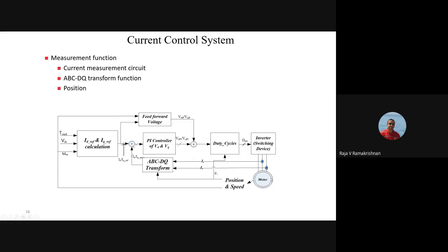It's a three-phase motor, usually a permanent magnet synchronous motor, because of the current density and torque density you get for the packaging, since our packaging needs to be small. Our motor needs to be small and provide a lot more torque for that area, so the torque density is higher. So basically we have a current sensor, a position sensor, we sense, and then we have an open loop torque system.